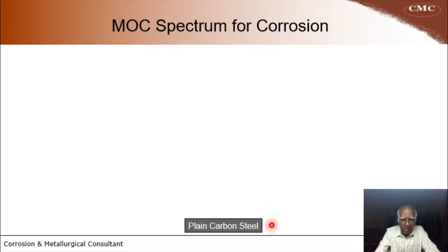This is very good with respect to manufacturing and availability, but unfortunately this is highly corroding. The corrosion resistance can be incorporated by giving a paint coating. The paint coating will survive most of the corrosion situations except the following conditions.